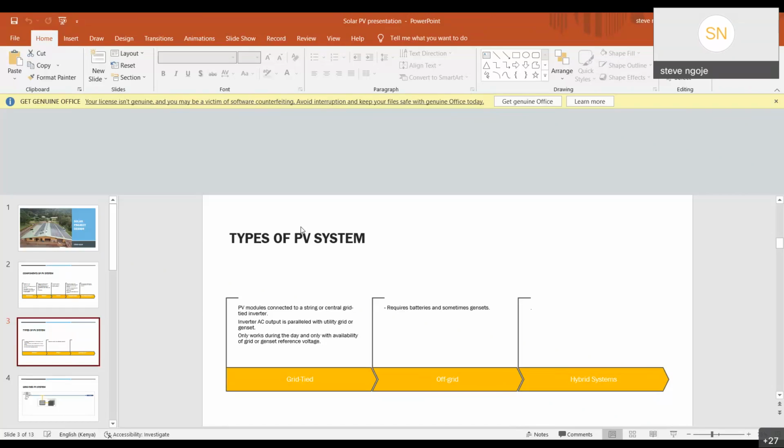The incoming grid cable, or whether it's a bus bar, depends on the electrical layout of a facility. But you have to connect them in parallel. It's easier to have the grid-tied system when it's only connected to the grid than when you have to incorporate a genset or a generator. Reason being, it's easy to control, and in this case, solar is always given higher priority.